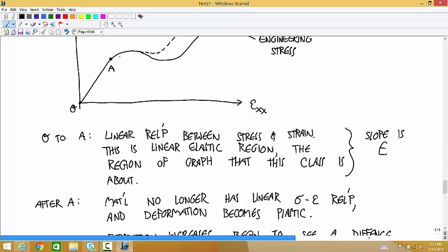Once you get to that plastic region, the material is getting less stiff. You can see that the instantaneous slope gets lower and lower, right? And it would sort of make sense that after you get into these big deformations, the material would start to get softer, more flimsy, more compliant. But there's actually this weird thing that happens. After you stretch it a little more, it starts to get stiff again. It's strange, but it's called strain hardening.